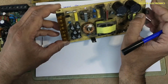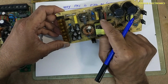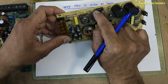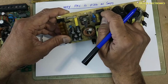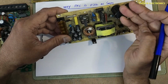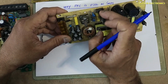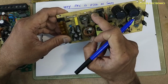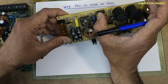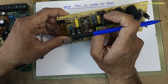If we see this power supply, there is the line input, EMI filter, bridge rectifier, capacitors. Here is a selector switch, 110 220. If you are operating this power supply on a 220 volt utility line, at that time this switch will be selected at 220. If we are operating in a 110 volt condition, at that time we will select this switch to 110. So it is a manual selection.